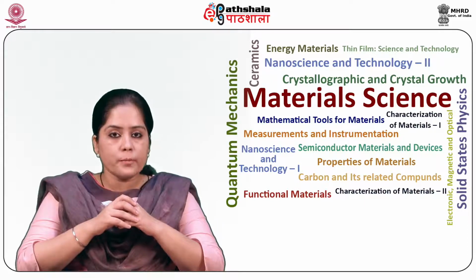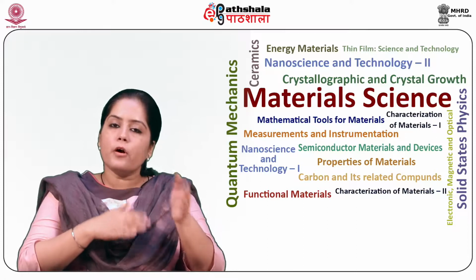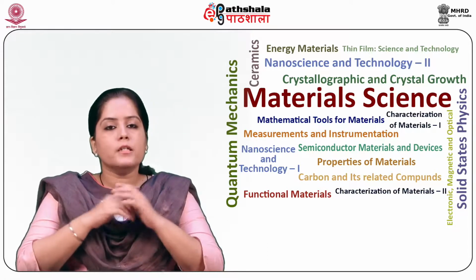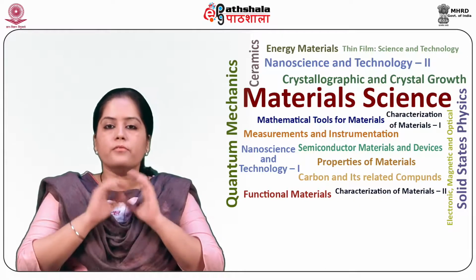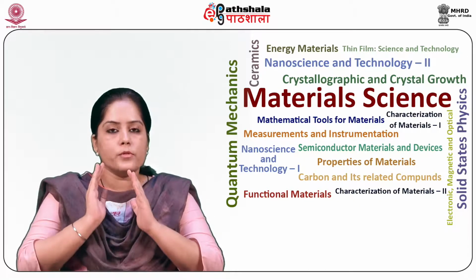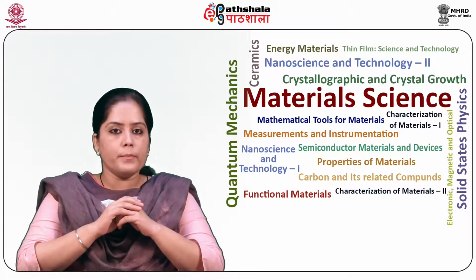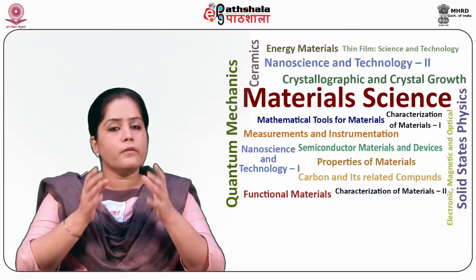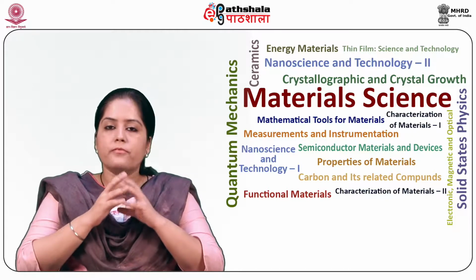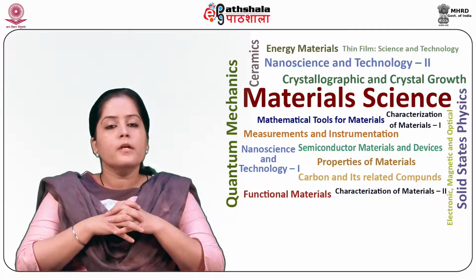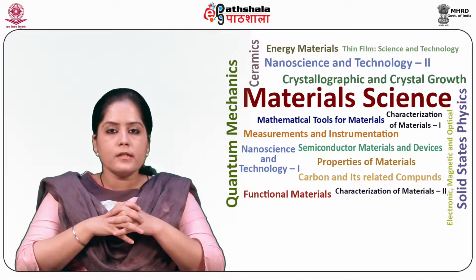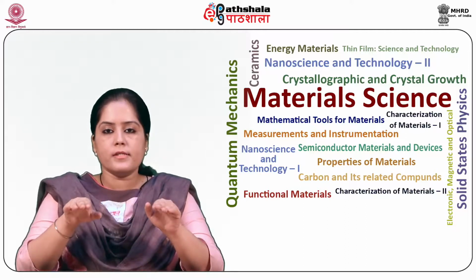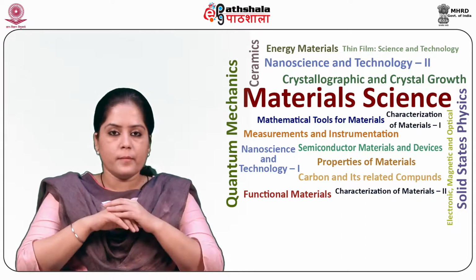Capability for stoichiometric transport from the target material to the substrate surface. In other words, reproduction of the exact chemical composition of the complex material in the deposited film. Reliability, high rate of deposition, use of laser as an external source of energy leads to a highly clean process without filaments.